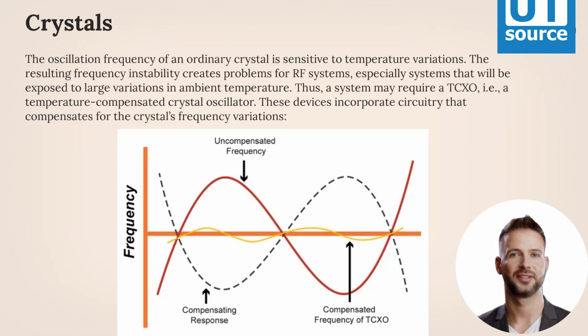Crystals. As in other types of circuits, crystals are a fundamental means of generating a stable frequency reference. However, in digital and mixed signal design, it is often the case that crystal-based circuits actually do not require the precision that a crystal can provide, and consequently, it's easy to become careless with regard to crystal selection. An RF circuit, in contrast, may have strict frequency requirements, and this calls for not only initial frequency precision, but